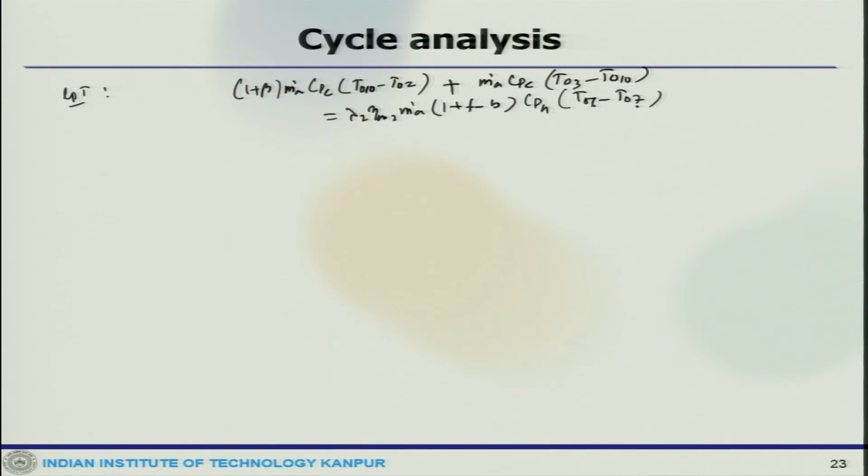Now, the flow in the jet pipe is frequently associated with a pressure drop, mainly due to skin friction. So, the pressure upstream of the nozzle is slightly less. So, we get P naught 8 as P naught 7 into (1 minus delta P jet pipe), and T naught 8 would be T naught 7. Now, finally, we come to the nozzle.